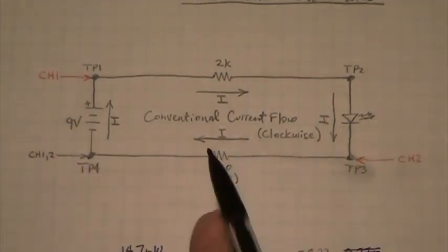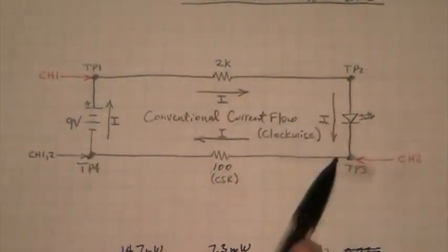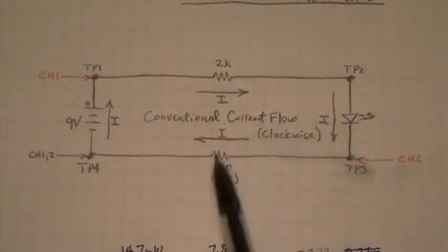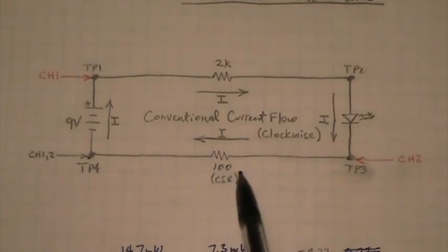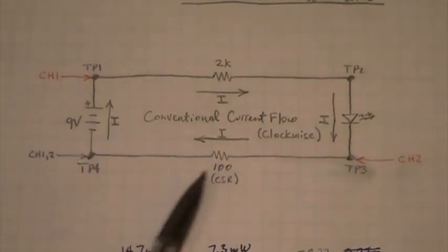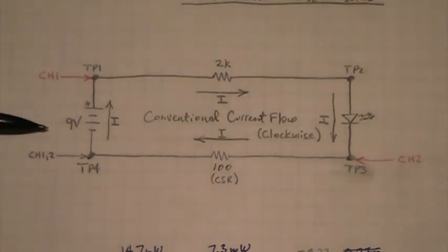We physically can't do that because of the isolation problems, but we can do it electrically inside the oscilloscope and we have the same effect. So when we invert the channel 2 current probe, when it multiplies by the positive battery voltage here, we will end up with a negative power, just like we did when we computed it with the calculator.